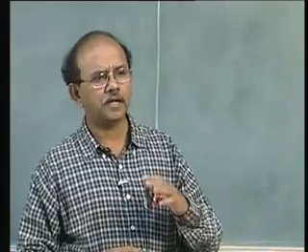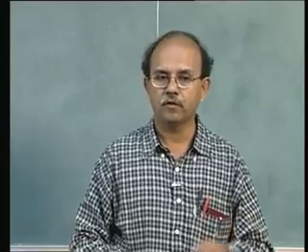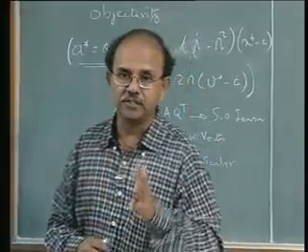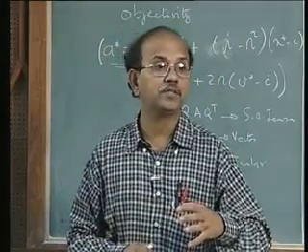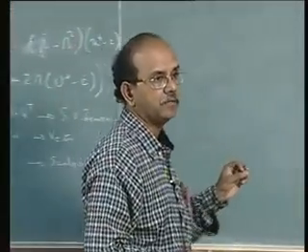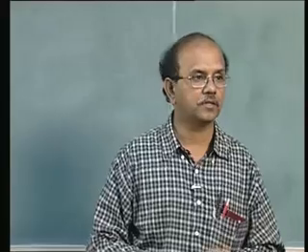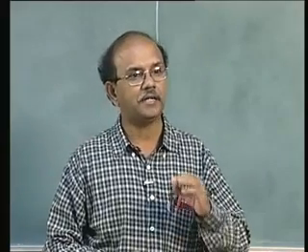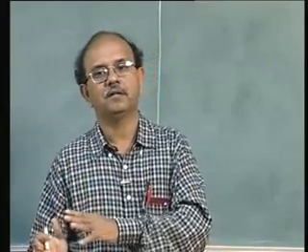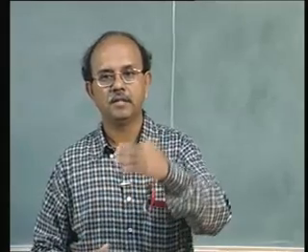Before we proceed, just a point of comment: there are some constitutive equations put forward, for example, which analyze asphalt and other things, where you make some conditions. You say that the constitutive equation is not valid if Q as a function of time is given to the observer. In other words, you say that I am violating material frame indifference, and what I am violating is actually the observer's motion with time.